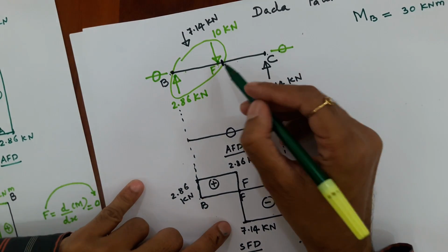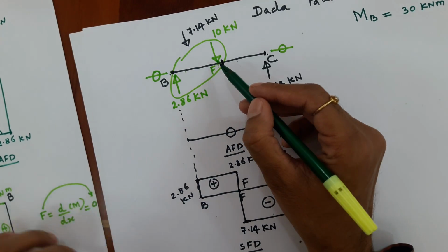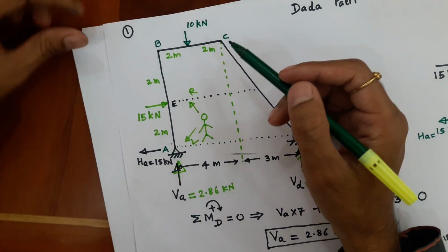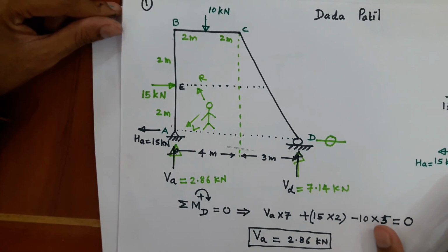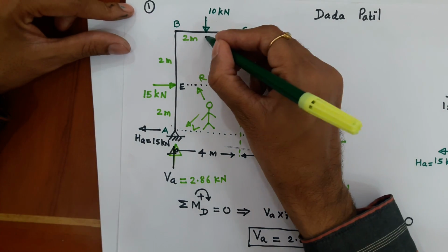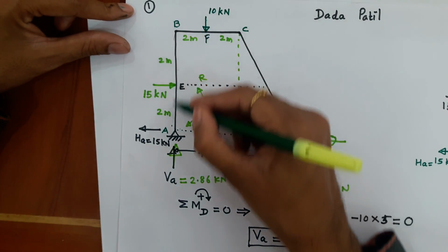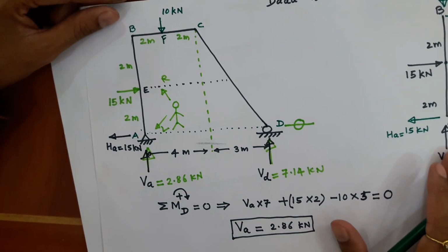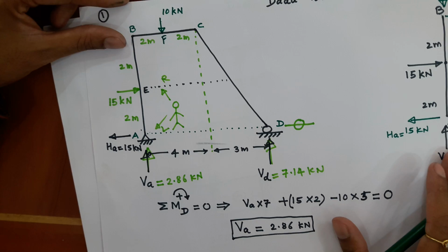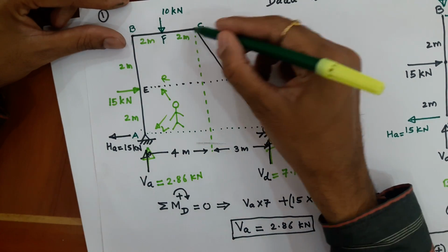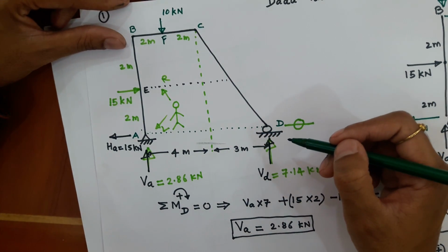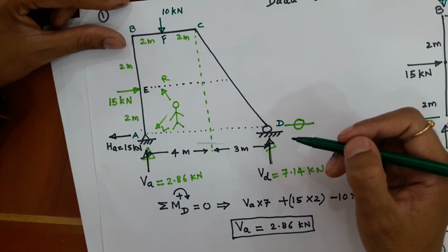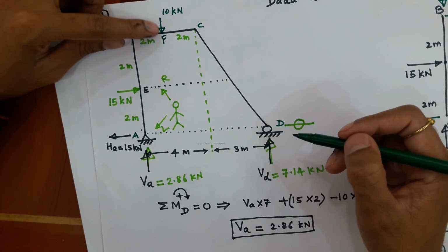Now next will be bending moment at F. So again there are two options. You have the liberty of either considering FBEA or FCD as per the basic definition of bending moment. Now considering FCD will be more convenient and time saving. So let me try that.